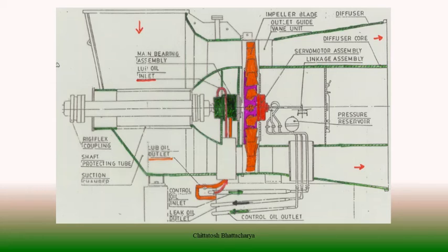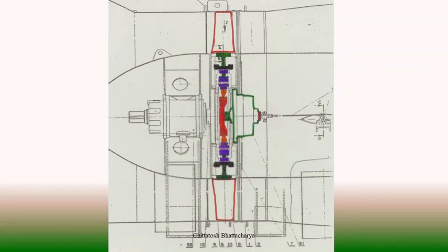These fans are specially accommodated within the diffuser with a hydraulic servo motor fitted with a control oil supply arrangement, and with this control oil supply they can tilt the individual blades in unison, which are coupled together, and that way we can regulate the gaseous fluid flow.